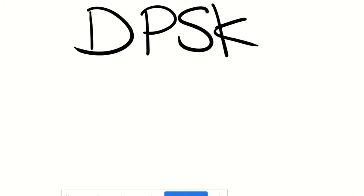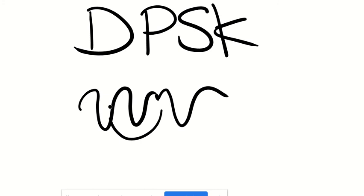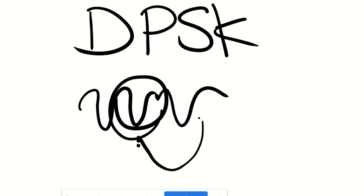You look at the signal before, and the signal before that will be your reference in terms of phase. So there is no carrier phase reference. That means that the phase of the received bit is compared with the phase of the previously recovered bit, in general form, without going into detail. That's DPSK.